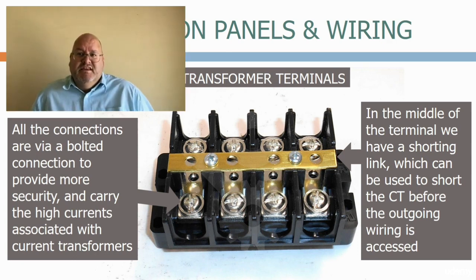If an energized CT is left open-circuited for even a few minutes, the internal voltages generated can damage the main windings, which will mean the replacement of the current transformer, an expensive business. This limitation needs to be designed into the CT schematics and wiring during the design phase and built into any maintenance schedules to ensure that it cannot happen under any circumstances.